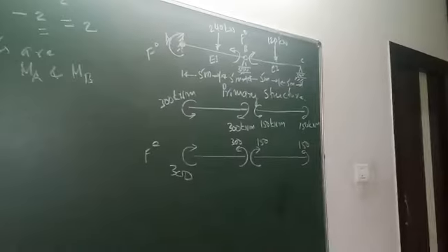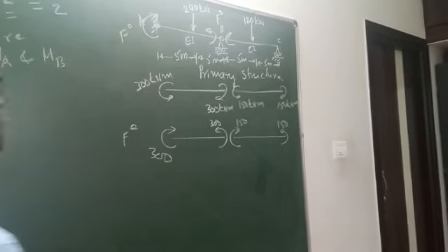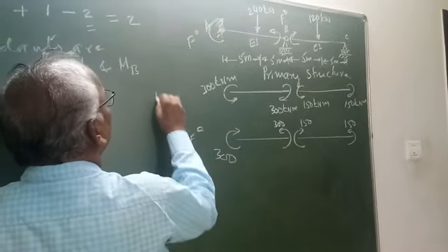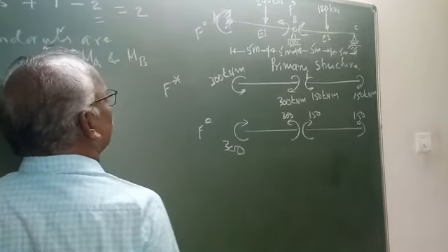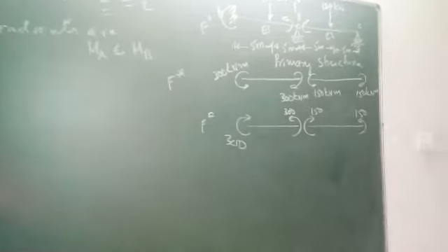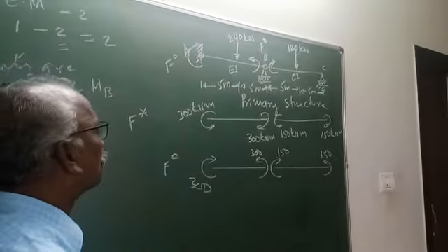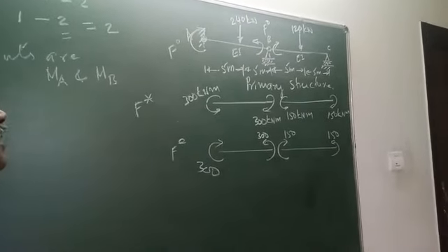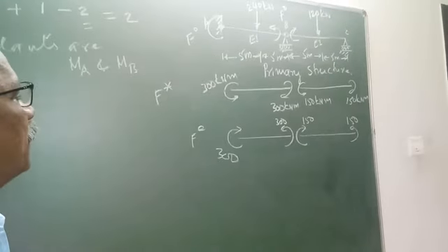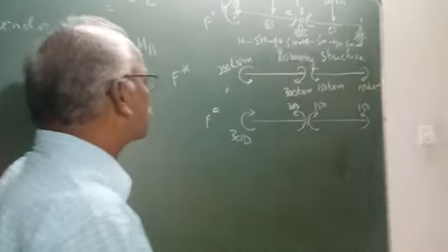Now we have to form the system forces. System forces will be resulting from the application of the external forces. So this will give you the F star values. F star values are the system forces resulting from the external forces. In the given problem, A is a fixed end. Therefore, that will take the moment and will not transfer the moment to the span. So we need not bother about this because it is a fixed end.